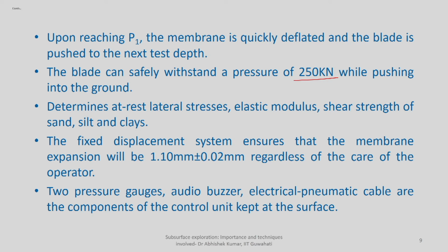So based on these two measurements, you are actually able to determine at-rest lateral pressure, elastic modulus, shear strength properties, and even the over-consolidation ratio and many other properties, just by measuring these two parameters at the site. The fixed displacement system ensures that the membrane expansion will be 1.1 mm plus or minus 0.02 mm regardless of the case.